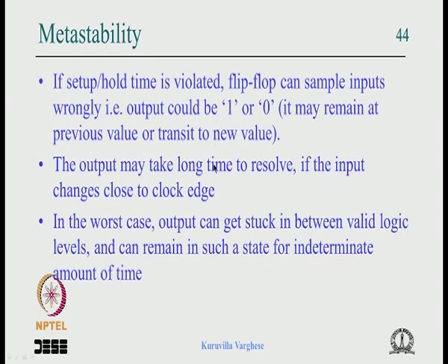If setup hold time is violated, the flip flop can sample the input wrongly, and the output could be 1 or 0. That means if it was 0 before, it may remain at the previous value or transit to a new value. Output may take a long time to resolve if the input changes close to the clock edge. In the worst case, the output can get stuck in a non-logical value and remain in such a state for an indeterminate amount of time.